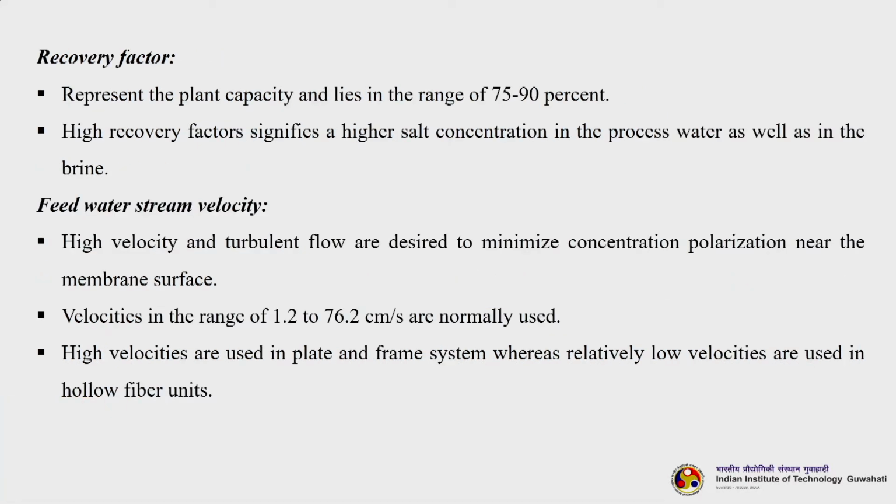The next one is recovery factor. It represents the plant capacity and usually lies in the range of 75 to 90%. A high recovery factor signifies a higher salt concentration in the process water as well as in the brine.